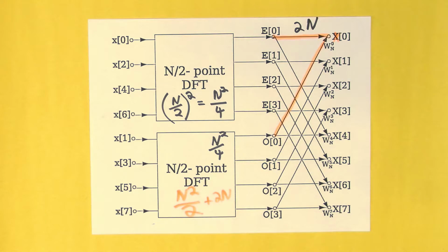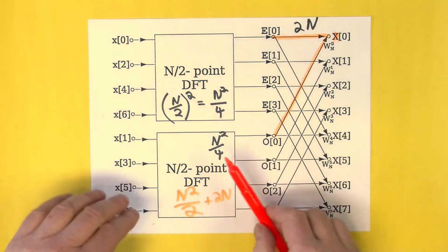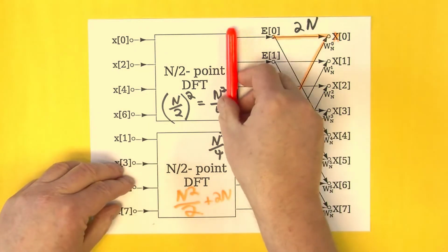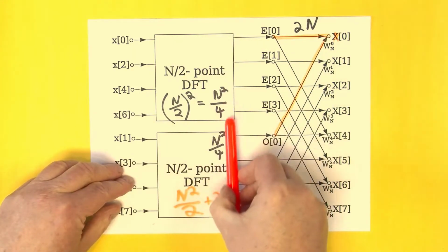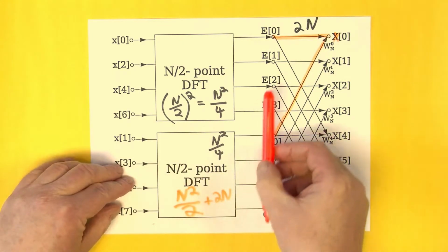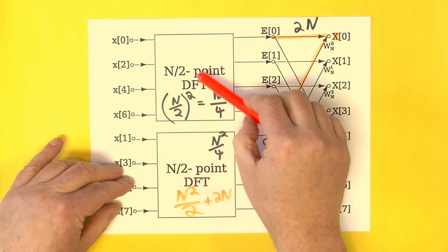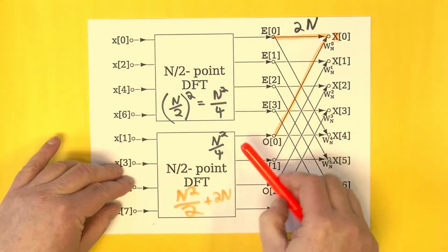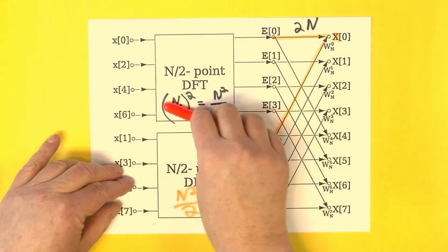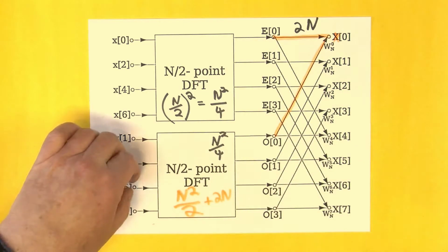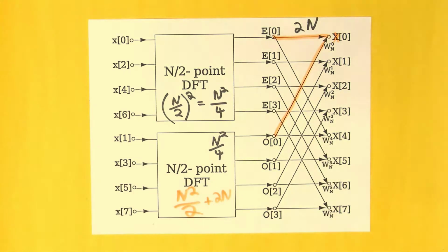And in fact, it turns out that if you now repeat this process and take these 2 half-size FFTs each and split each of them up into half-size FFTs and work on them the same way, and then take those smaller ones and split them up and keep repeating it till you have essentially one data point left, you end up with a massive saving in computation.